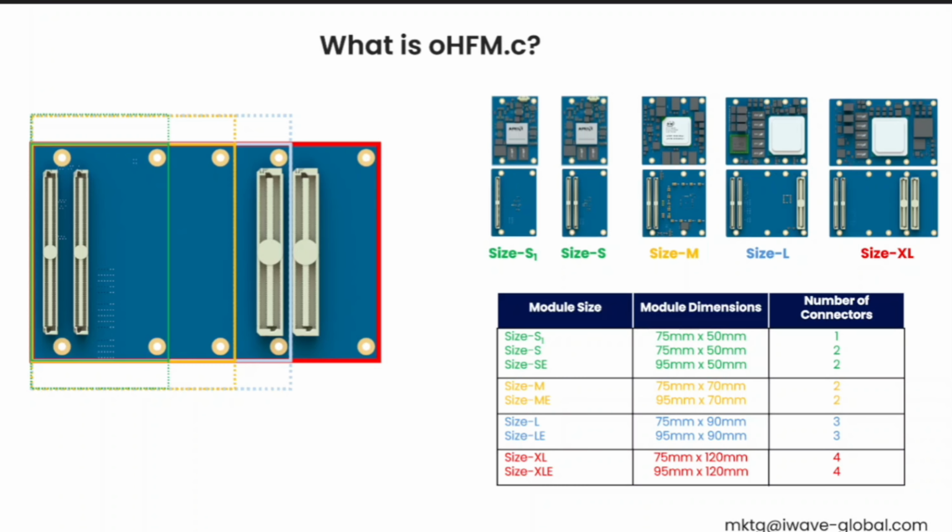With connector 1, we get one low-speed transceiver bank, power control signals, the FPGA and other basic interfaces. Connector 2 additionally adds three high-speed transceiver banks, connector 3 adds 6 high-speed transceivers, and connector 4 additionally adds 7 high-speed transceiver banks.